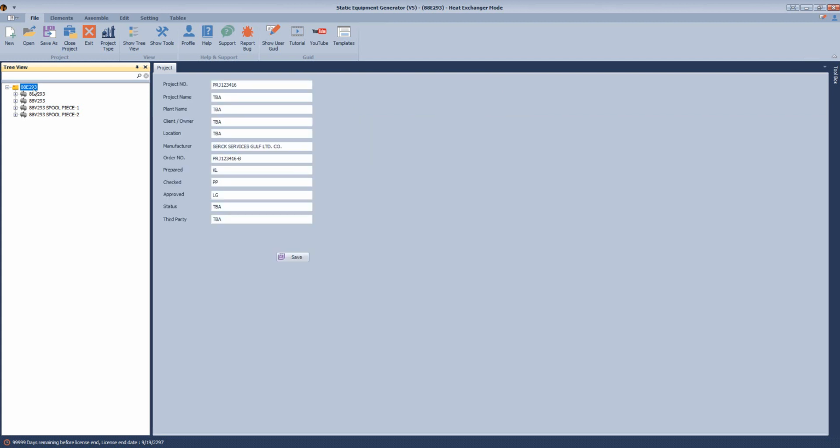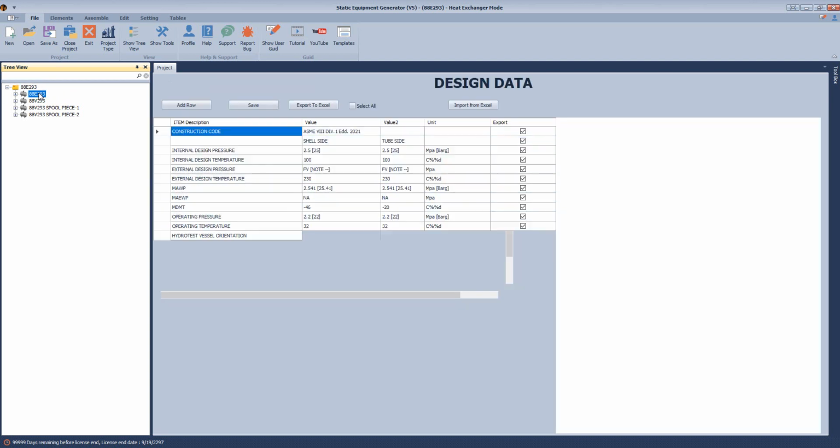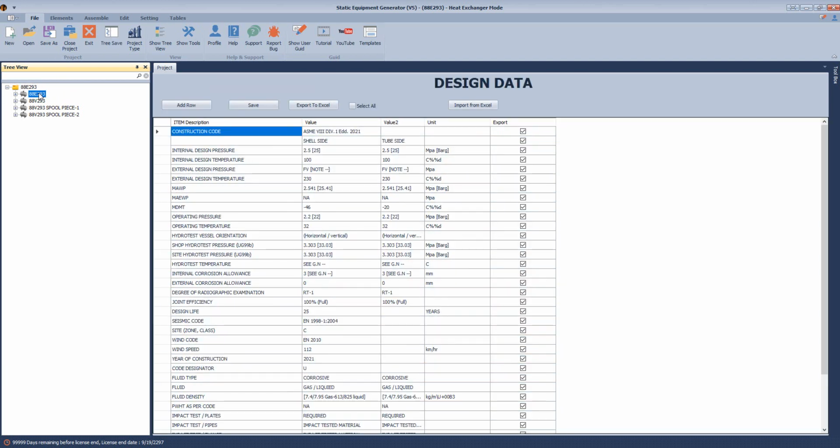Okay. And if you try to create a project that includes all of those items, that means on the Autodesk Inventor side, you will generate an assembly with the same name as the vessel assembly in the same folder, and that will not be possible. Okay. So from the concept of Autodesk Inventor, it is not possible to create another assembly with the same name.